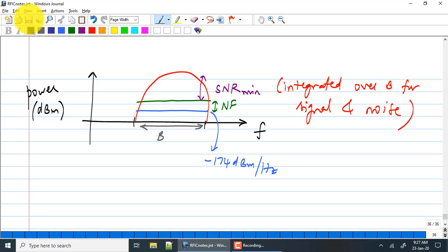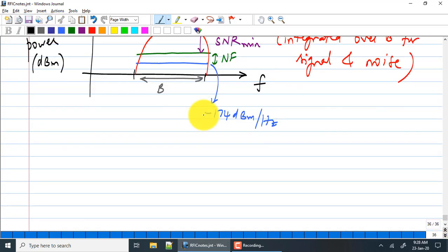Now, I want to go the other way, right? I want to start increasing my input power. Okay, how high can I go? Linearity limits, of course, right? So now I need to specify the linearity of my receiver. So we have looked at noise. So as usual, like I said, I'm trying to set the topic so that we leave it as soon as possible. So to design any circuit, you need to know both limits. You need to know the noise limits and the upper linearity limits. Fundamental specifications of any circuit.